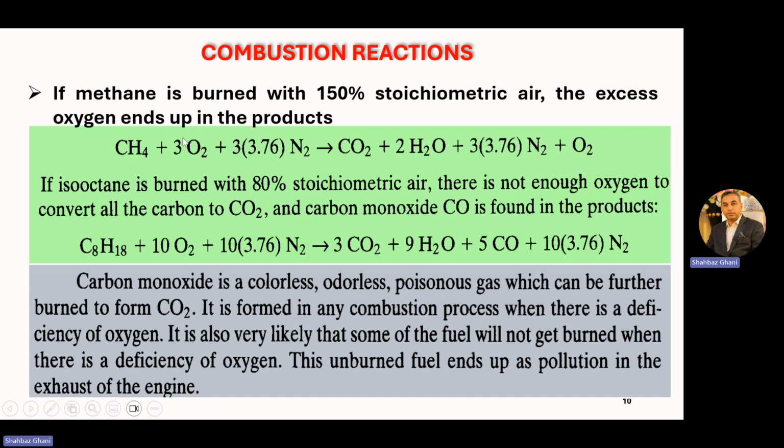So now the chemical equation for the simple methane will be CH4 plus 3O2 plus 3.76 into nitrogen, giving 1 mole of carbon dioxide, 2 moles of water vapor, plus 3 moles of nitrogen, 3.76 plus, and due to the excess air, excess oxygen will be there.